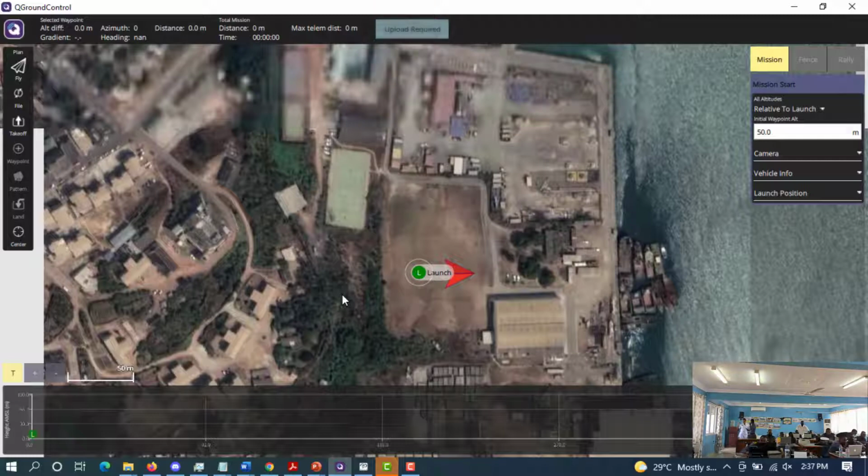Okay, so takeoff 60 meters, transition distance 300 to 800. Please, you cannot come below this. And then we have to fly into the wind. We already know the air resistance. The manufacturer is saying 50 kilometers per hour. So if the wind that is coming is more than what the drone can take, it will have issues on the aircraft. Okay? So that is the first part.